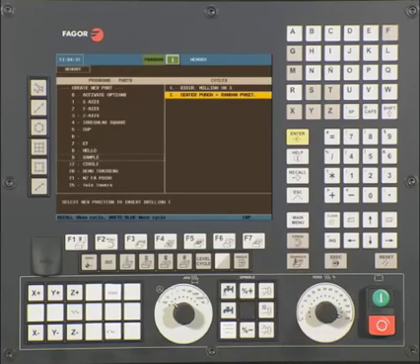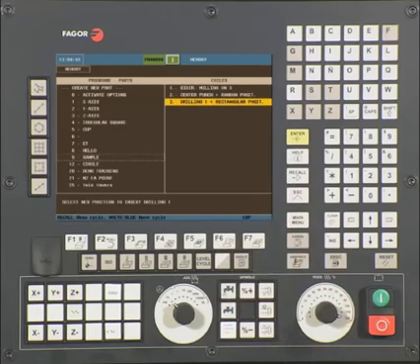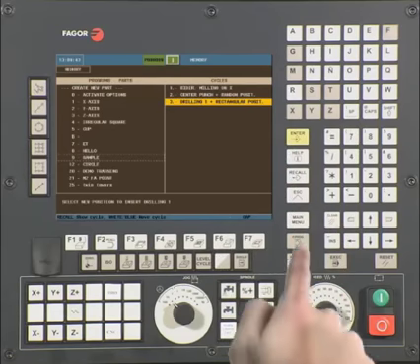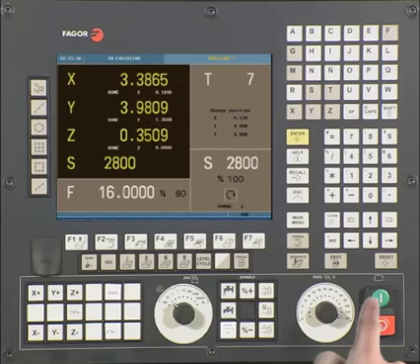Press the P program key. At this point, we should still be under the program we have created. If not, navigate back to the program. Once there, press Enter to insert the drilling cycle and rectangular grid pattern operation into the program. To execute the cycle, press Escape twice. You now see that there is a cycle start icon at the top of the screen. Turn down the feed rate to 0 and press Cycle Start button to begin executing the cycle. You will need to increase the feed rate after pressing the cycle start.